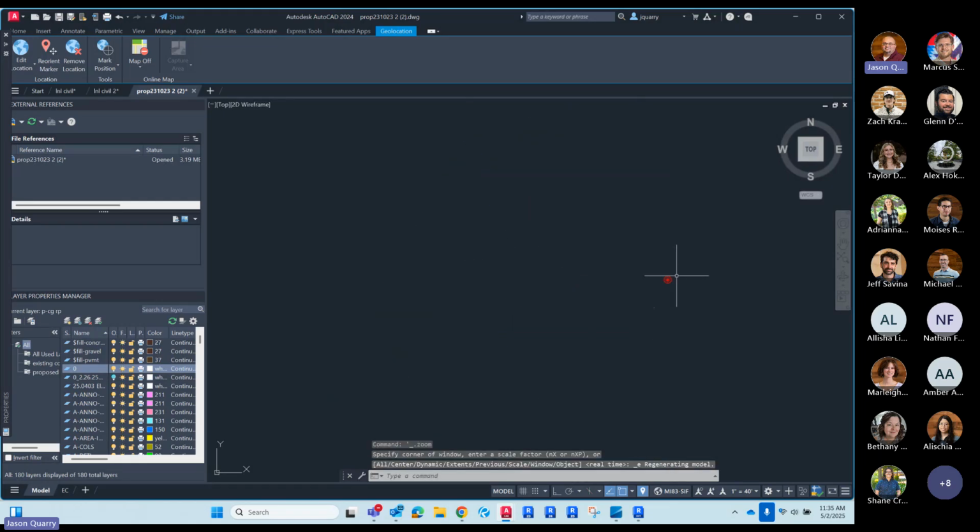See how far away these lines are from this? You've got to zoom way out to see how far away from the origin it is. So when Revit brings in a CAD file, it wants to bring it in based on the origin. Now, I haven't tested this. You may be able to manually select center to center placement, which might get a little bit easier for you, but the majority of us go with origin to origin because it makes sense, right? When you're trying to import it.